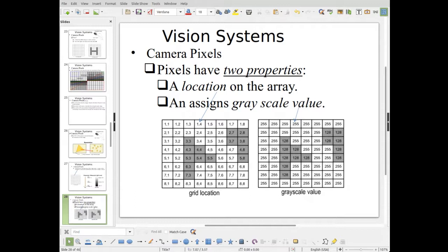Okay, so there's actually two parts of the CCD. The one part is where is it? Okay, so remember we had X going in the horizontal and Y going down. And so we're going over 1, 2, 3, and then we're going down 3. So this part starts at pixel number 3, 3. So this gives us the X and Y, and then by looking at all of them, we could also tell the rotation of that part.